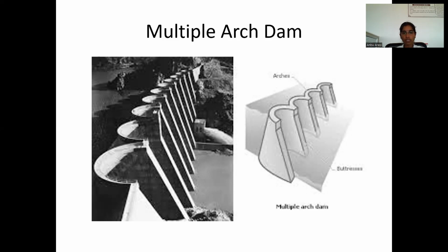That is thick arch dam. Another one is thin arch dam. Thick arch dams can be built where the crest chord height ratio is between 3 and 5. The chief geological criterion is that the rock must be absolutely reliable to bear 3.5 megapascal or more without any appreciable settlement. There is a substantial saving in material compared with that of gravity dams. Thick arch dams are difficult to design on paper but are well determined from trials on models. Thin arch dam.